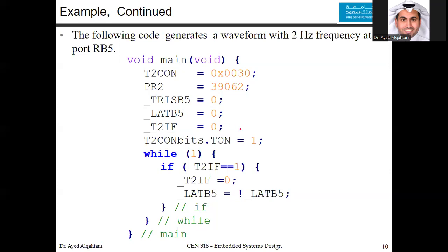Now, it's very important to know, for any timer when you start it, you must set the flag to be 0. This flag will be asserted to 1 once the timer expires.